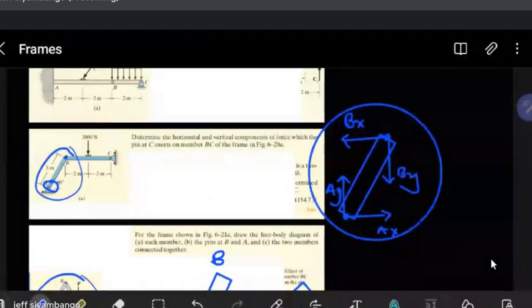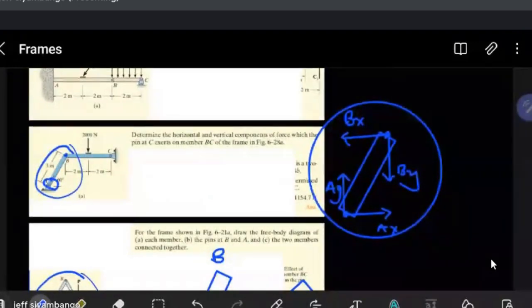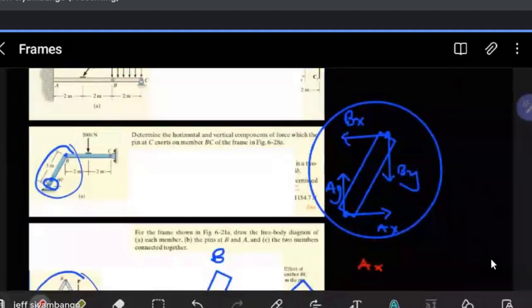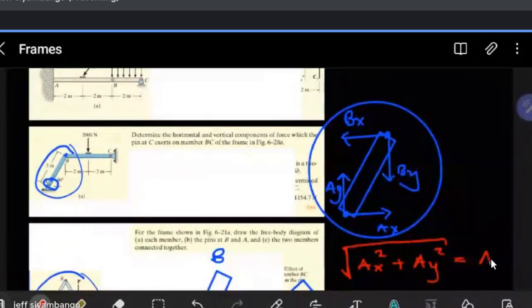Okay, it's just a try. You said it's two forces in general and not the component parts of the forces. Yeah. So it's like we have BX, BY, AY, AX, but we're looking at them in terms of A and B. Yes. So what you have to see here is that if you combine AX and AY, squared, square root, what this will give you, of course, is just the force A. So the force A, a combination of these, you expect it to be in that direction.